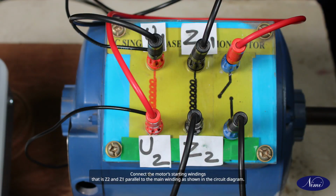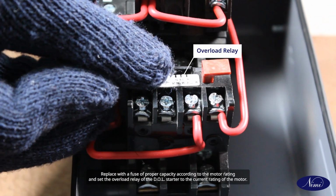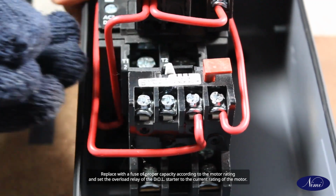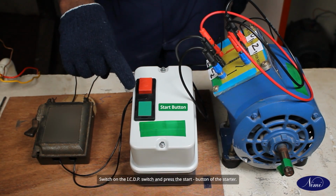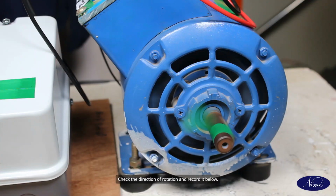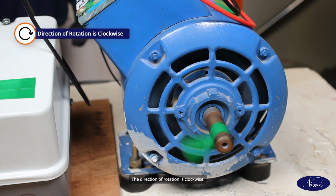Connect the motor's starting windings, that is Z2 and Z1, parallel to the main winding as shown in the circuit diagram. Replace with a fuse of proper capacity according to the motor rating and set the overload relay of the DOL starter to the current rating of the motor. Switch on the ICDP switch and press the start button of the starter. Check the direction of rotation and record it below. The direction of rotation is clockwise.